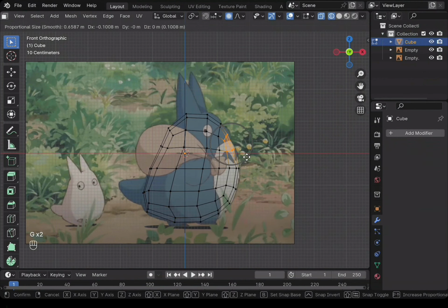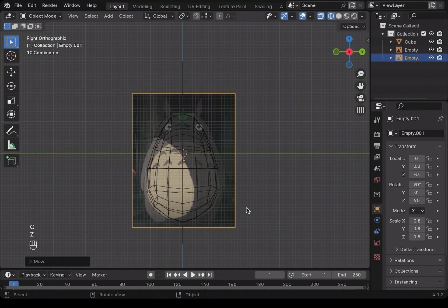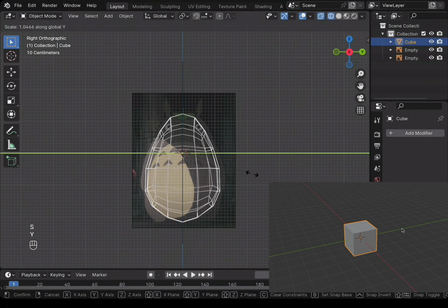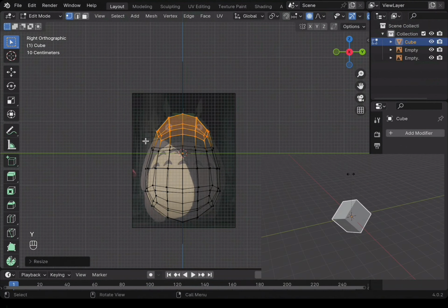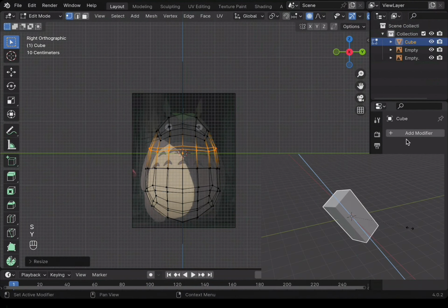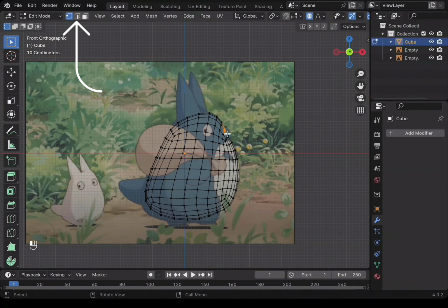To control the direction these controls will happen on, type in the axis or angle. For example, GX to move on the X-axis or R45 to rotate 45 degrees. Double-clicking the axis will move the object along the axis before rotation. You can also change from points to edge to surface at the top.